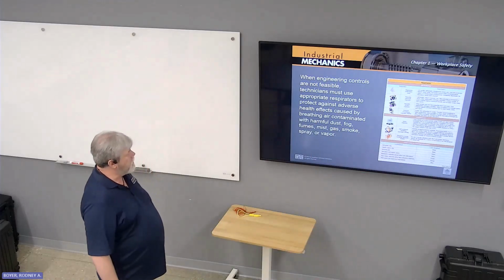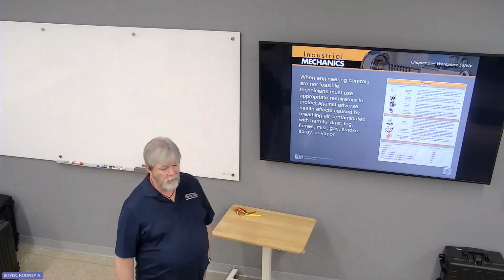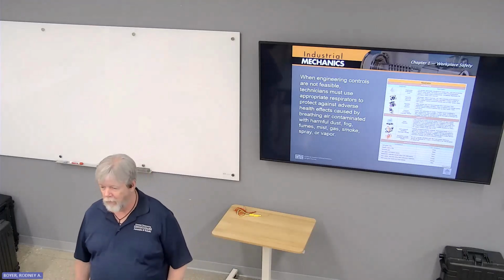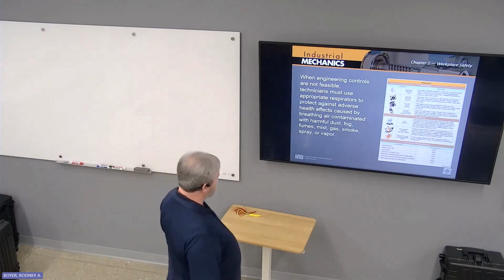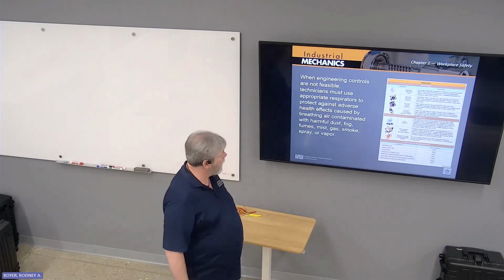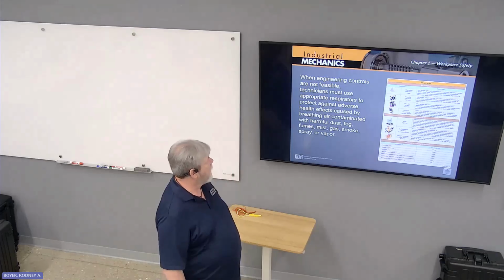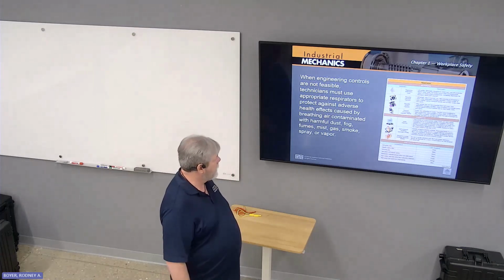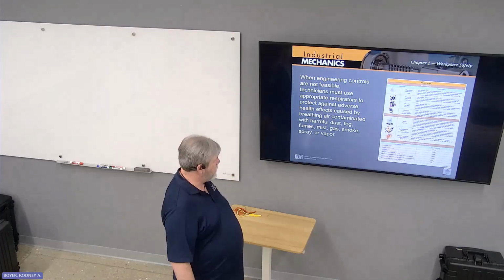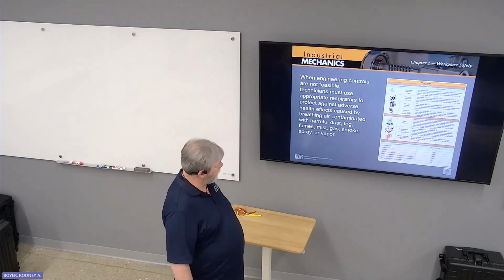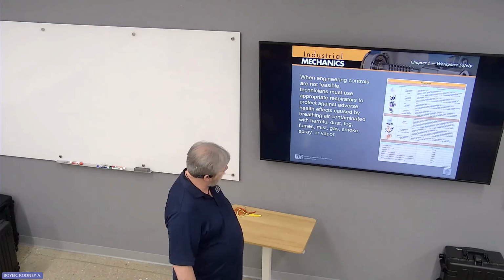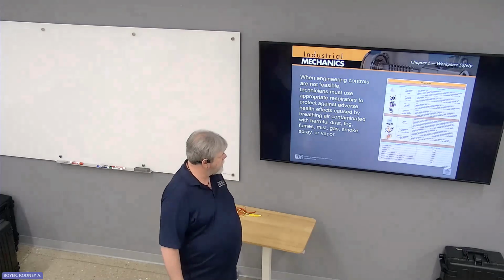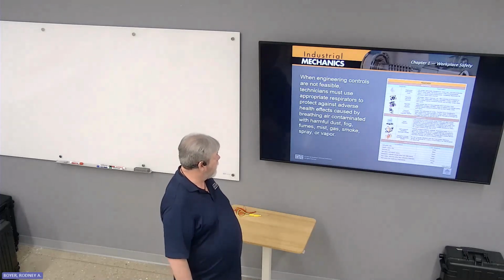Okay, the color of the cartridges and or the containers tell you what the cartridge or canister is good for. White is acidic gases only, black is organic vapors only, green is ammonia gas only, yellow is acid gases and organic vapors, purple is radioactive except for tritium and noble gases, orange is dust, fumes, and mists other than radioactive, and olive is other.